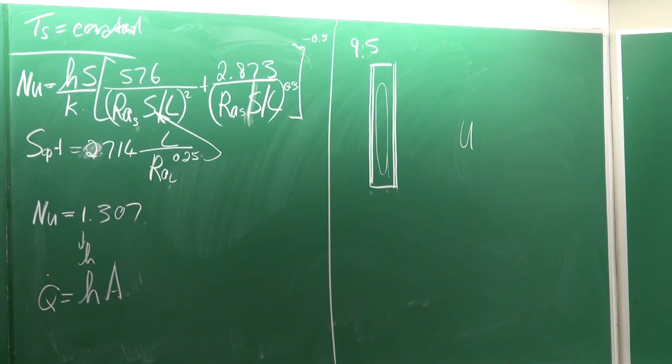But typically, if you look at single glazing glass, 3 millimeters, then the U factor will be about 10. Okay, the U factor will be about 10. If you look at triple glazing glass with a 12.7 millimeter air space, then the U factor goes down to about 1.19. Or if you use argon inside, then it would go down to 0.8. So from 10 to 0.8.